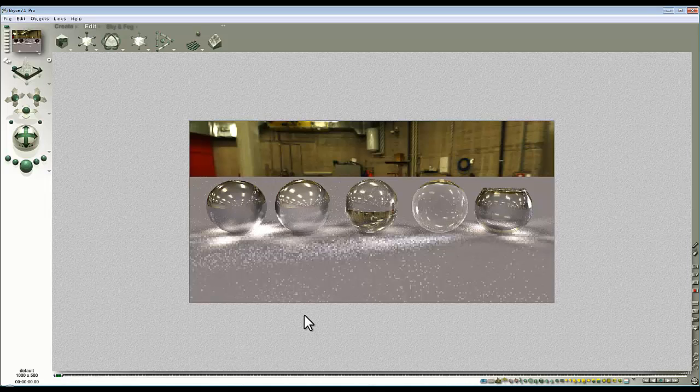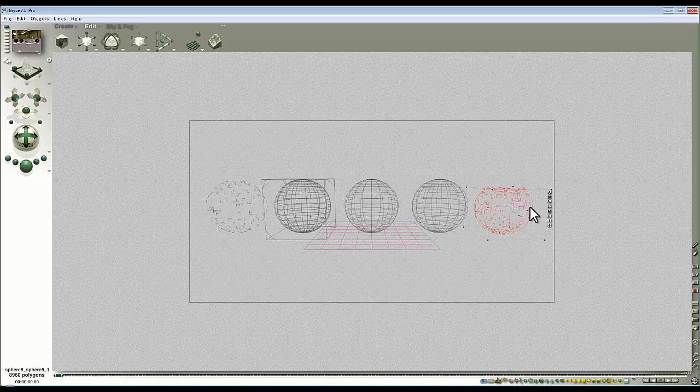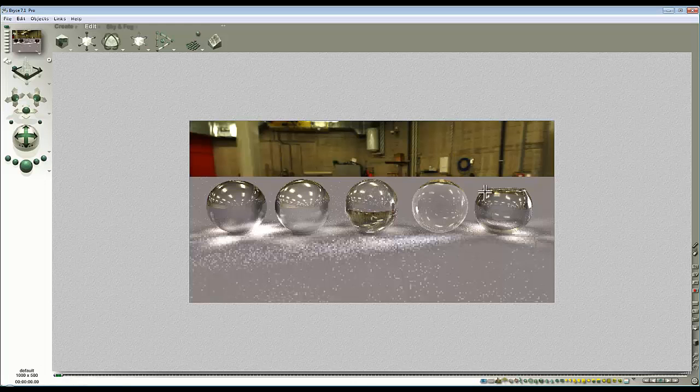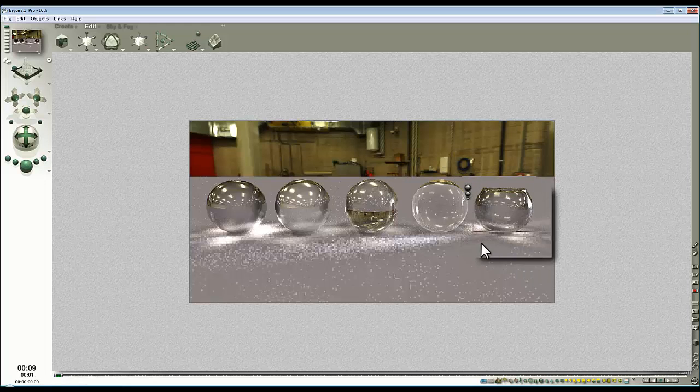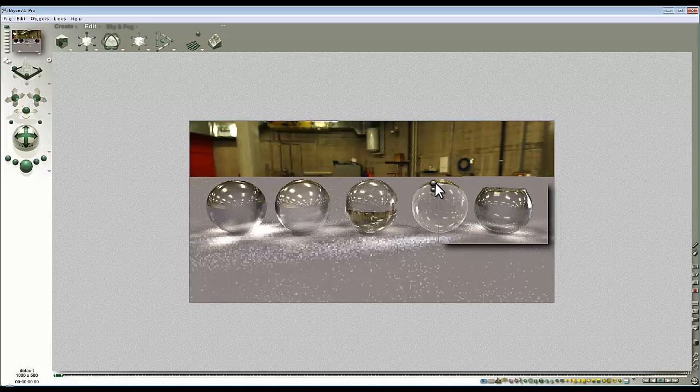given we've gone on quite a while now, I think we'll just have a quick modification of this. To make the glass lighter, we can lower the refractive index, but that changes its optical properties as well, so you just got to be a bit careful of that. So let's try 135 and see what effect that has in terms of the material, its appearance, as how heavy it makes it look as a glass. So lower the refractive index again. It's not having a radical difference on its appearance at the moment, but it will do when it gets closer to that of air.